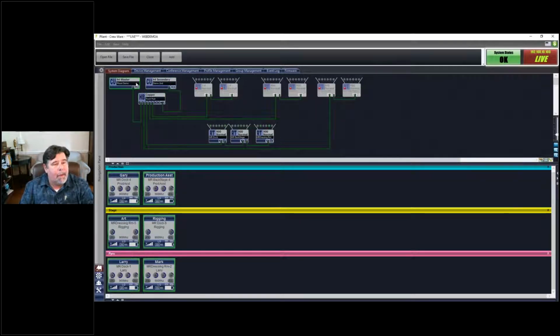A thing to note is that most of the work I'm doing with the system, when you're loading everything onto it and tying into it with your computer, is through the master. That's where you make your LAN connection, and the master is the only control unit that's going to store the CCF file. The secondary unit does not need a CCF file. It's just a drone. It basically wakes up and lives off of the logic that's inside of the master.